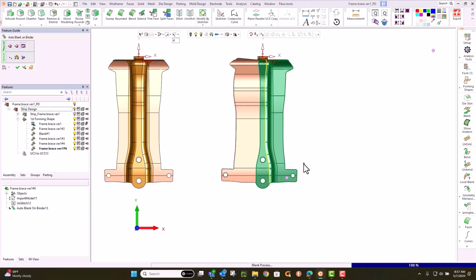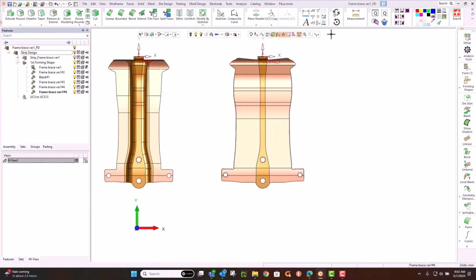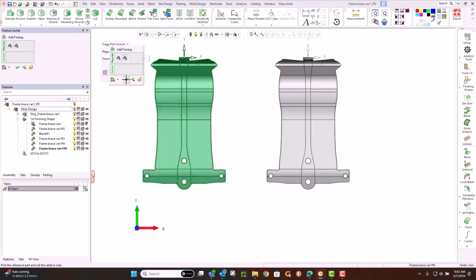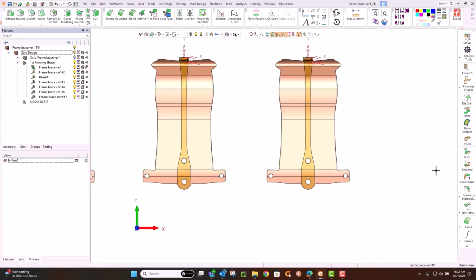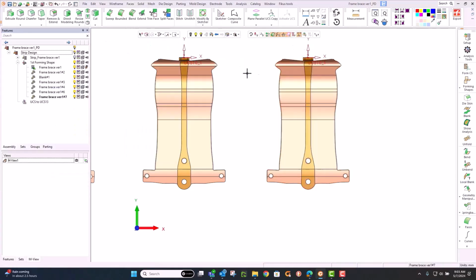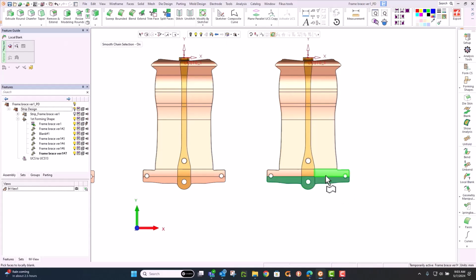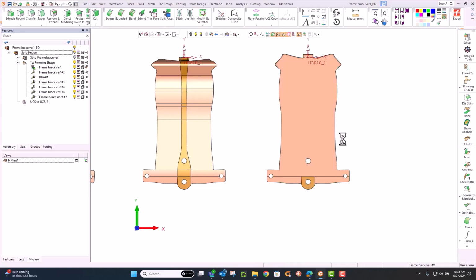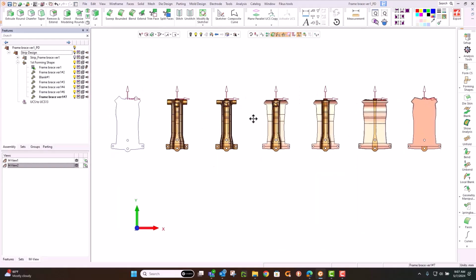So here we have what you might call your curved form. We want to lay that out flat and see exactly what it would look like as a true blank. So make sure all the pieces are together here and just do what we call in this case a local blank operation. And it will take the curvature out, laying it flat for me. So I can compare it to the initial blank, or I can go ahead and start working with it as is. Eventually these forms are going to be the things that populate my strip, which I can place in any order I want. It's just a matter up to me how I lay that out.